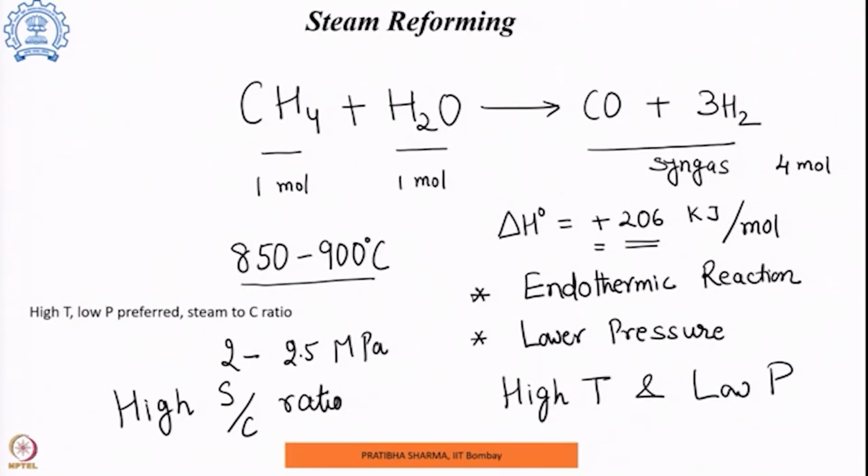The pores within the catalyst filled tube can get filled. So, the voids get filled, thereby reducing the flow of the gases, and the increased tube wall temperature can also lead to tube failure. So, in order to avoid all those, a high steam to carbon ratio is preferred in this particular reaction.